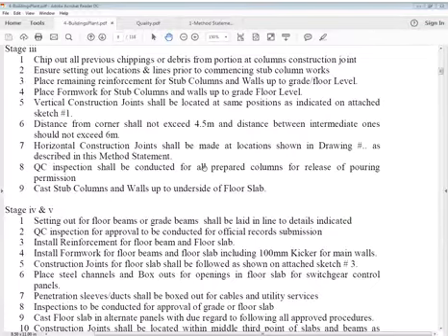It's not only in slabs; it can be in columns as well. In columns, when you stop concrete somewhere, and next time you have to do the slab or another part of the column, the vertical part, you have to scabble that completely, expose aggregates, and clean all steel. Generally when you do slab, beam and column junction along with monolithic slab, it's called a construction joint. Sometimes there is a very small vertical piece of column, called a neck column. This is generally coupled, so it doesn't matter for the neck column. That has to be prepared as a construction joint.